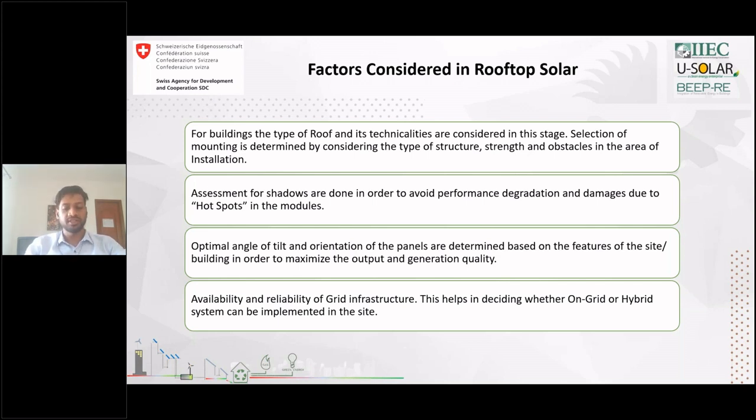For example, if it's a monsoon season and solar irradiation is not available to charge your batteries, the system will sense this, and as soon as the battery reaches critical levels, it will use the grid to charge the batteries. The entire system will act basically as a UPS, where storage is available in spite of solar irradiation not being available.